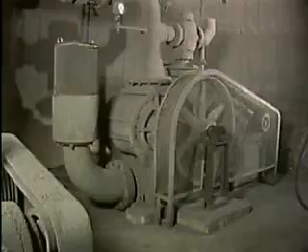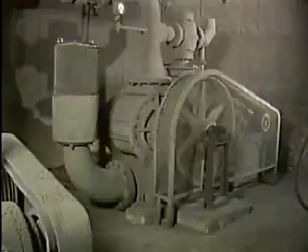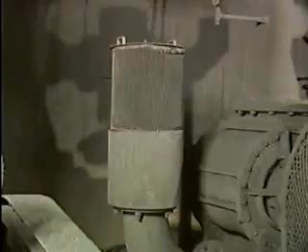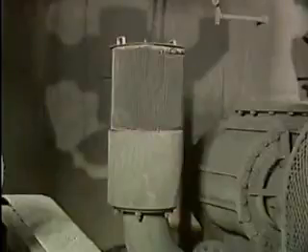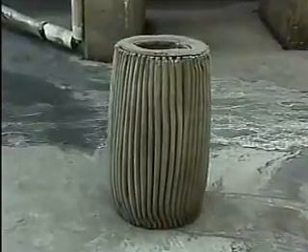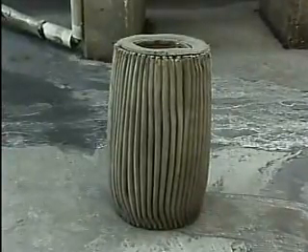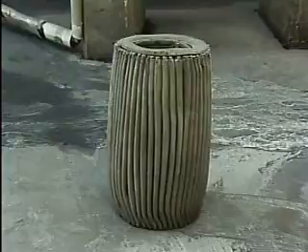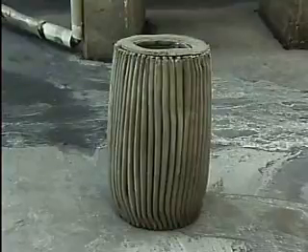Compressors often have devices or systems that remove foreign material from gases, remove excess heat, and provide lubrication. For example, filters are often used to remove foreign material from a gas before the gas is compressed. If small particles of dust or other foreign material are allowed to enter a compressor, they can cause the compressor to wear excessively and eventually fail. An air compressor typically has some type of filtering device in the intake line to remove dust and other foreign materials. The filtering devices are often paper or cloth filters.